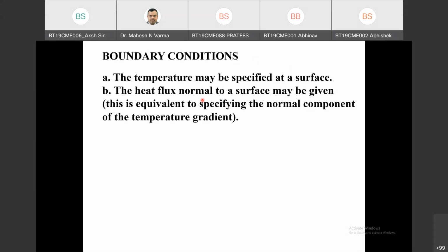Hello, sir. So what boundary condition will be the equivalent of this type of boundary condition shown on your screen? Liquid gas interface, zero flux condition. Yeah, zero flux condition. Flux may be given, momentum flux may be given. That is the liquid gas interface. Flux will be a zero flux condition. You can see here also it is exactly similar.